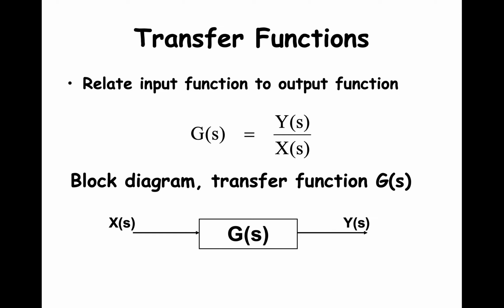We have mentioned transfer functions before, and we will talk about them again. Transfer functions are Laplace domain expressions that relate the input function in the denominator to the output function in the numerator. In a block diagram, the input function X(s) is transformed by the transfer function G(s) into the output function Y(s).